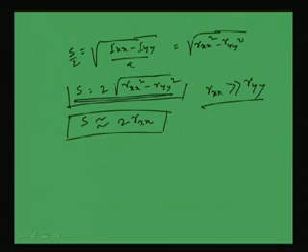So the spacing will become approximately 2 into Rxx. So this is how we can find out the optimum orientation for the compression member. Of course, remember this is explicitly for a compression member, meaning there should not be any moment. If moment is there, then again we have to see; we cannot generalize, we have to find out accordingly in terms of the magnitude of the moment.